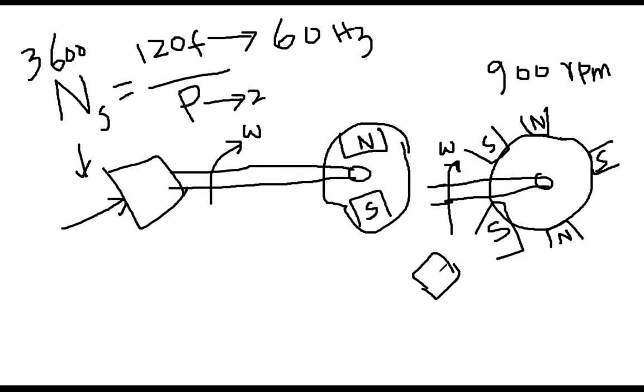And because the hydroelectric turbine naturally rotates at slower speed, consequently you have to choose a higher pole number. That's why this configuration. And in the other case, because naturally the speed is very high, to match with the 60 hertz, you cannot but put 2 or a maximum of 4. If it is 1800, then maximum 4. So it is not just what the pole number is or what the frequency is. It is the geography that determines the type of the pole, whether it is non-salient pole or salient pole. So everybody, could you follow me?